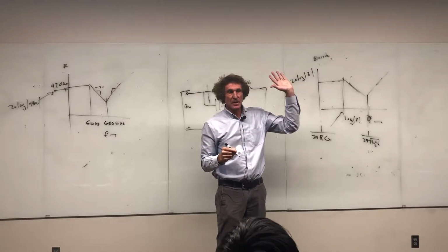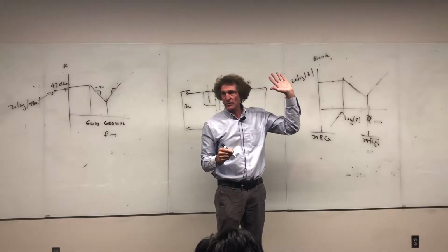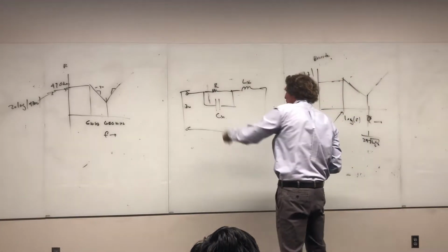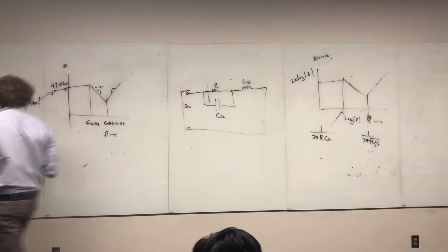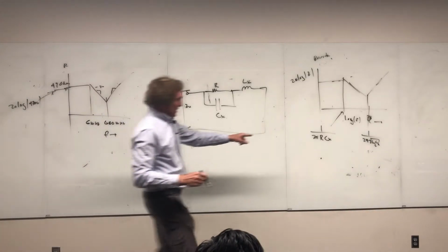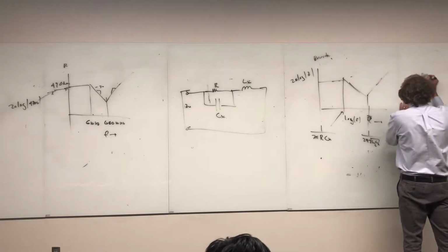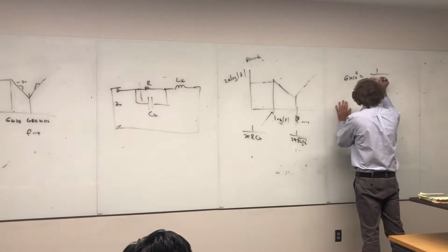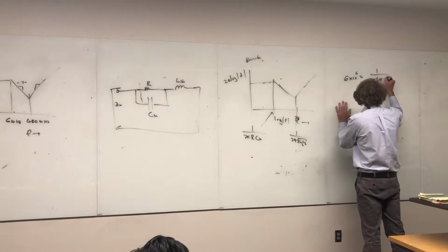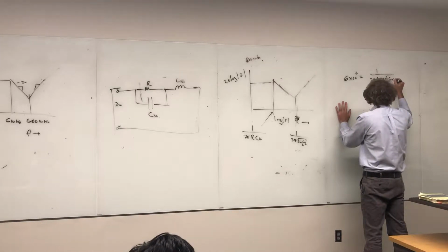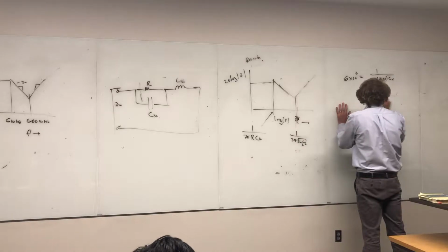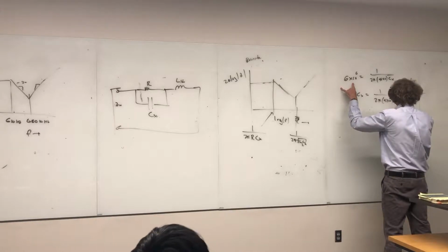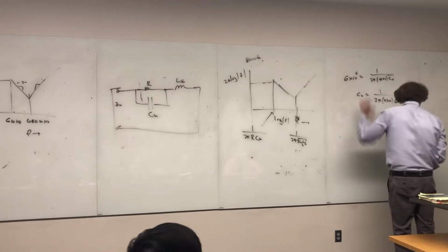Please make sure. I see it. All right. I drew this out for you and told you why it's the case. So you always start at this frequency right here. I know I've got R, and I want C, so I can find C because there's the break frequency. Here, 6 times 10 to the 6th would be equal to 1 over 2 pi times R, which is 4,700, times CX. Or I can say that CX is 1 over 2 pi 4,700, divided by 6 times 10 to the 6th. Can you give me that value?